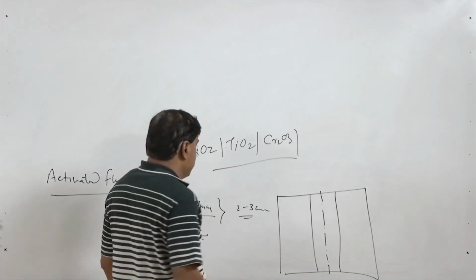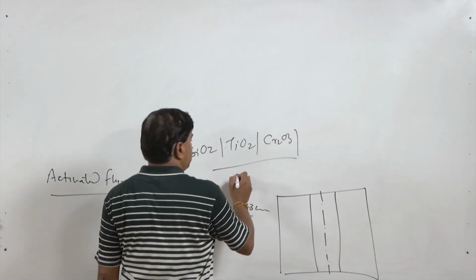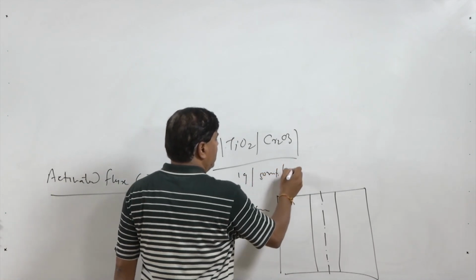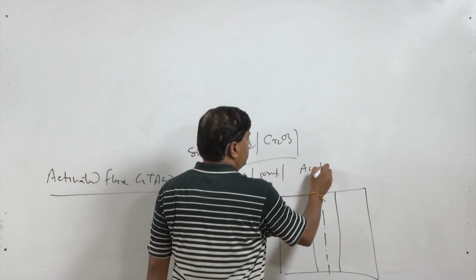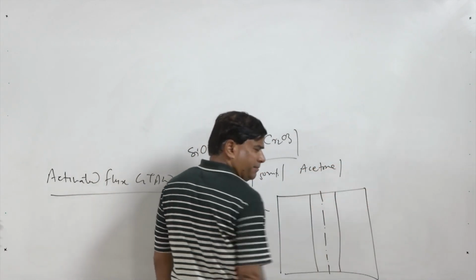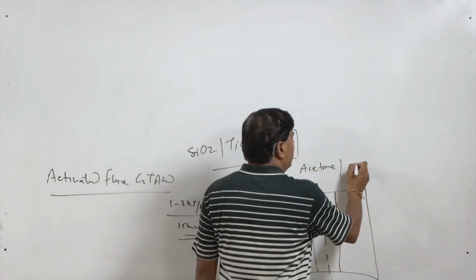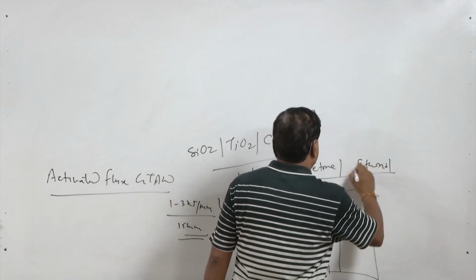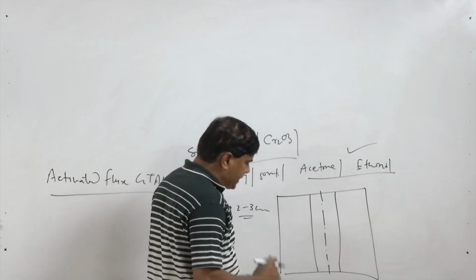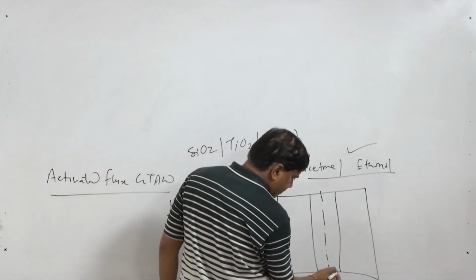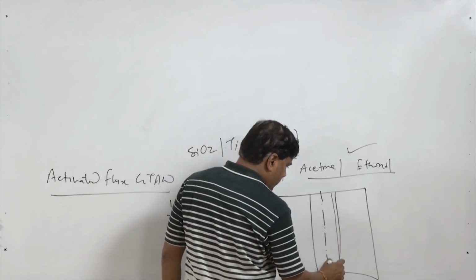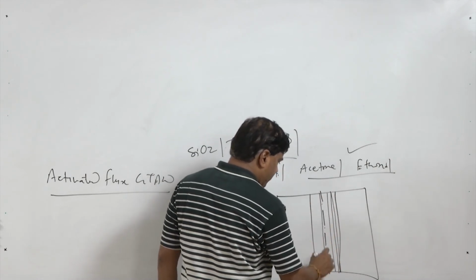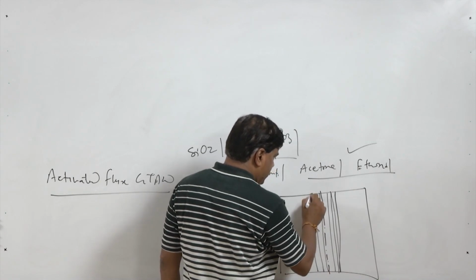These fluxes are normally used as 1 gram in 50 ml of either acetone or ethanol. A mixture is made in the form of a paste, and just one layer of paste is applied over the surface of the base metal to be joined.